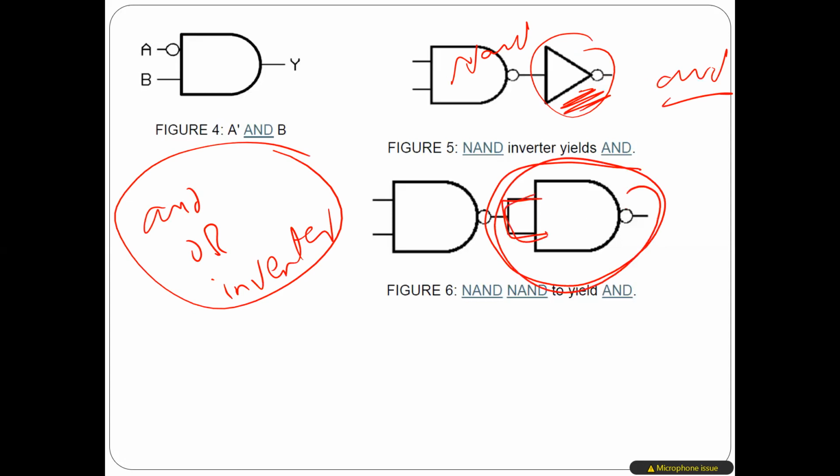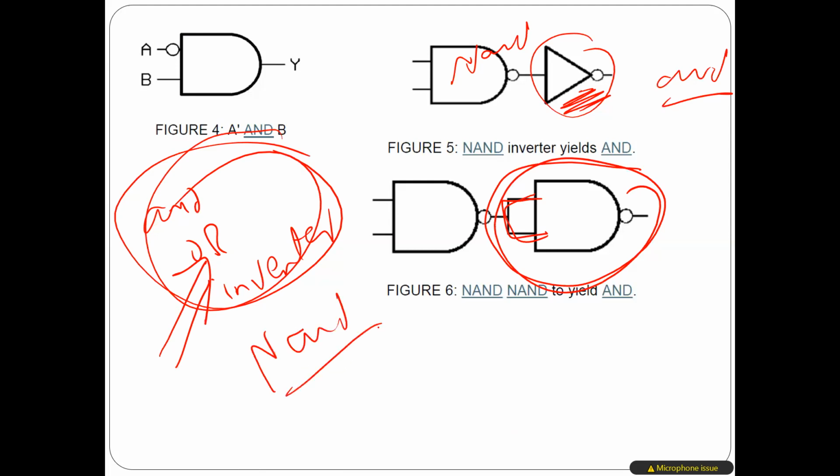So what I want to tell you guys, any logic circuit, okay? Let me summarize what I said, make it very easy. Number 1, any logic circuit can be implemented using these main operations here. Is that okay? Also, these 3 operations can be implemented using NAND. So in other words, any logic circuit can be implemented using only NAND.